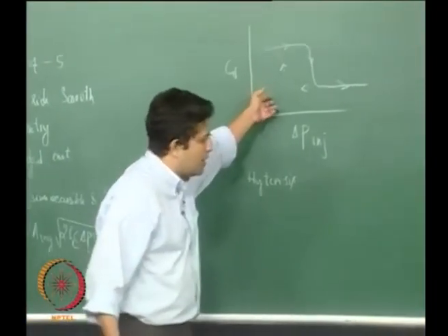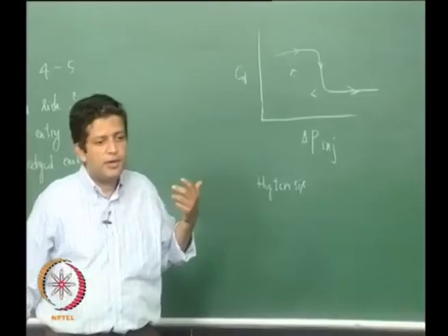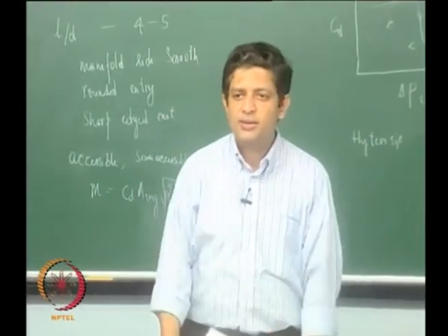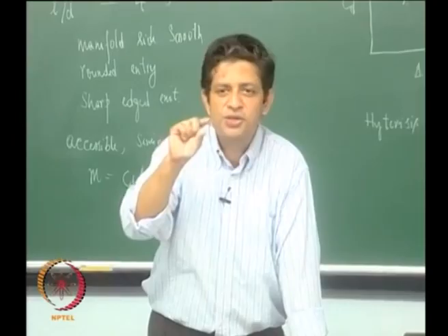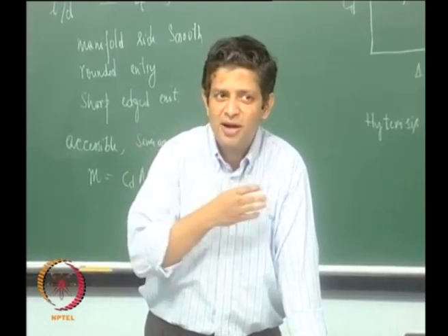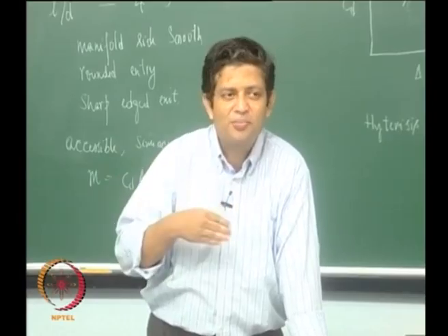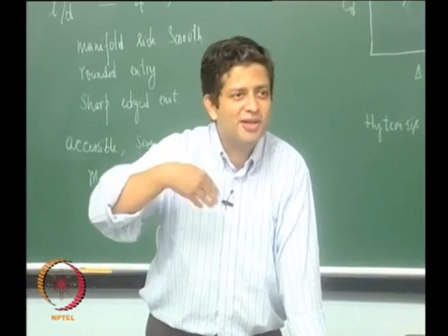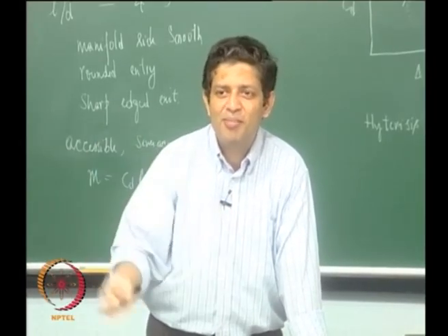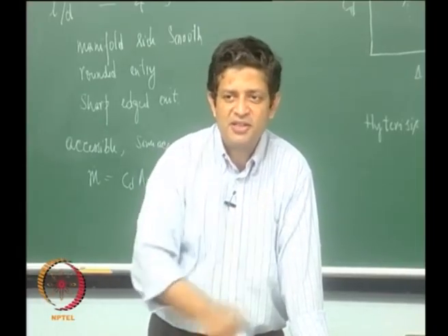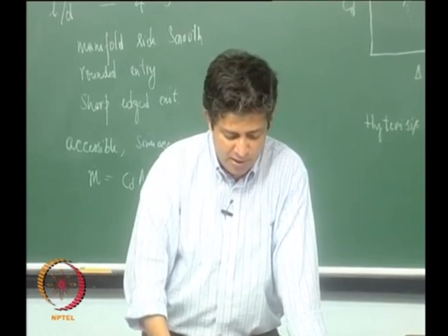Partly this happens because the fluid is going through a path, right? There could be flow separation and other things. Now if you are reducing the injector pressure, the flow separation process might not follow the same path while you are coming back, and that is why this kind of hysteresis is observed.